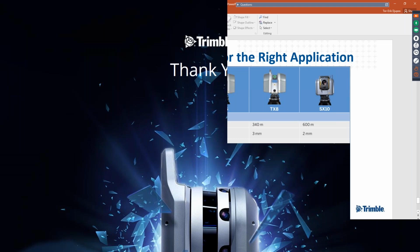And finally, we have, is the scanner self-leveling, which I think you covered. If you just want to run through that again, Ted. The scanner is self-leveling, yes. As I said, currently, as long as it is within plus minus 5 degrees, we will level it to better than 3 arc seconds. The scanner can be tilted all the way up to 45 degrees and we will still level it. The only thing we say is that it won't be within 3 arc seconds. So even at 45 degrees, we actually can level it.